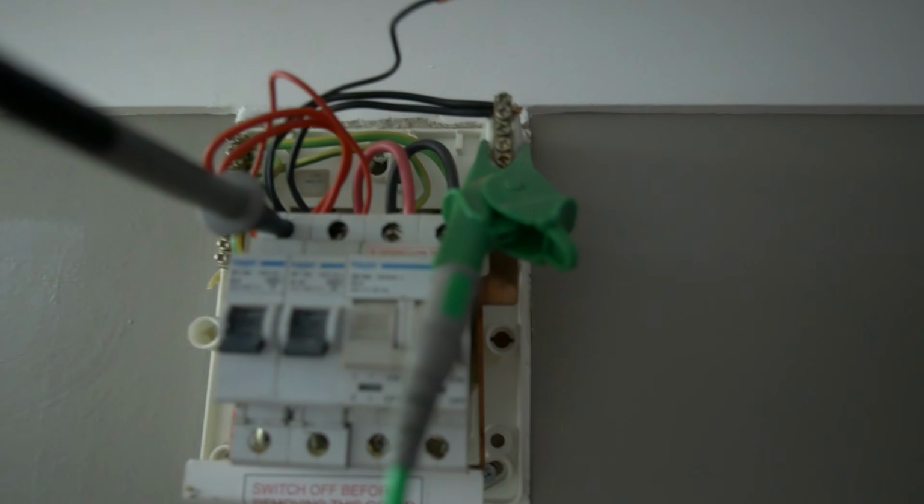And again, then you can do between your live conductors in this case. So I'll pop this over onto the neutral bar. Because we've unplugged everything, I've been round to unplug the TV, all the other sockets are unplugged, so there's nothing in circuit. If I probe onto the line again of this socket circuit and hit test, I would expect this to be very low, and we can see it's giving us a dead short.